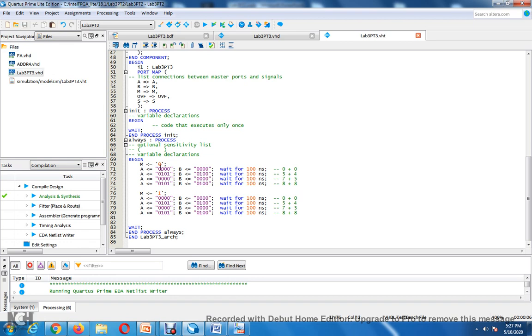Now I hope you understand what these vector constants do. The entire vector A through A2, A1, A0 gets assigned this way, respectively, okay, for this second line. A3 gets assigned 0, A2 gets assigned 1, A1 gets assigned 0, A0 gets assigned 1. Okay, so I got the same 4 problems, m equals 0 for addition, and then m equals 1 for subtraction.